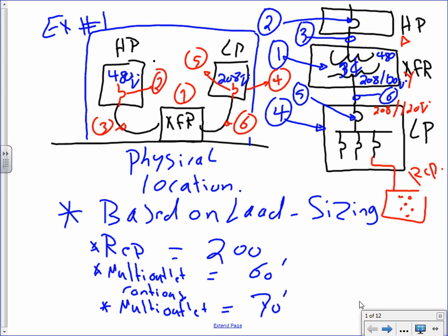So what I'm hoping is this will help you, Jeff, design your system. When I redline the riser for you, I'm going to ask you what size transformer you came up with for the receptacle panel, and what size transformer for the 208/120 bus duct. The example in our project has two, as a matter of fact. One is for the 208/120 bus duct, and the other is for the 208/120 receptacle panel. And then from here, we take a branch circuit and we feed receptacles.